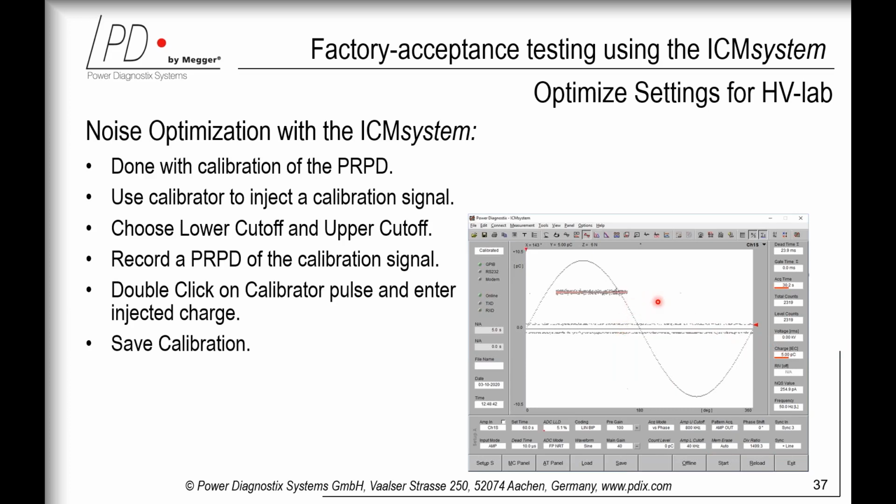One remark here, this is a rather clear and fine calibration. Here you expect no difficulties later on. However, if you have a strongly fluctuating noise floor influencing your PD pulse, or if you inject a positive pulse and get a negative value, you can be sure that you have some oscillations and have to take care of them later on. Especially when coming to the factory acceptance test, we then recommend to do dedicated calibration for each of the maps individually.